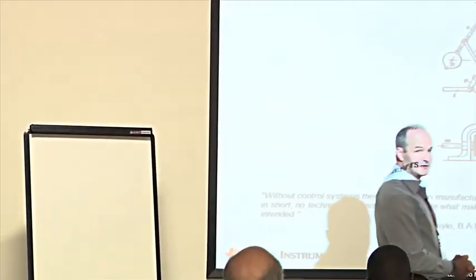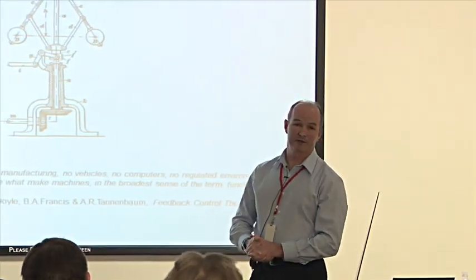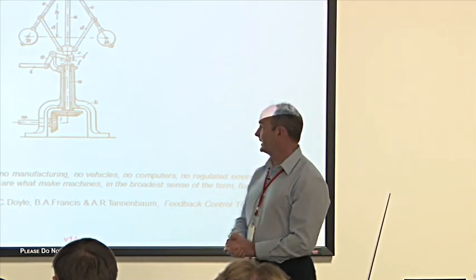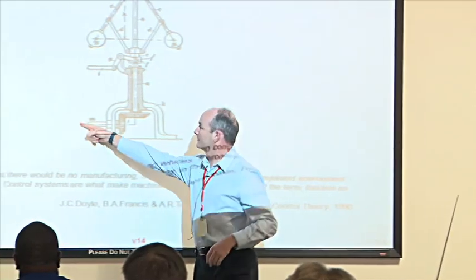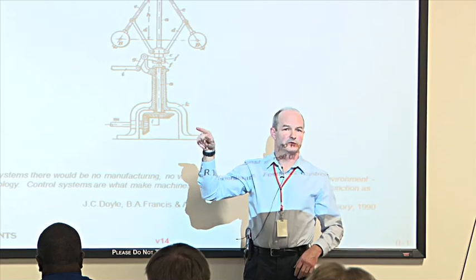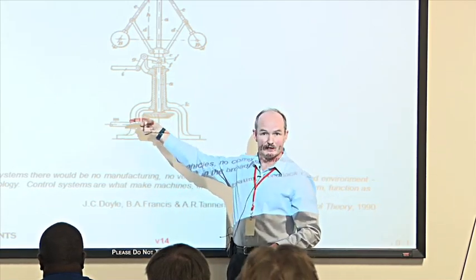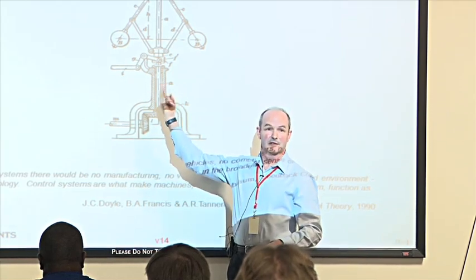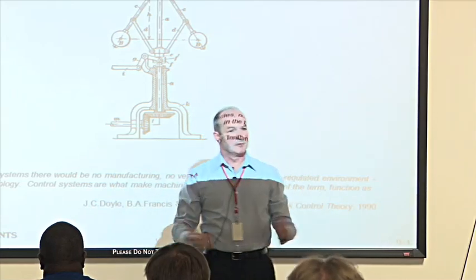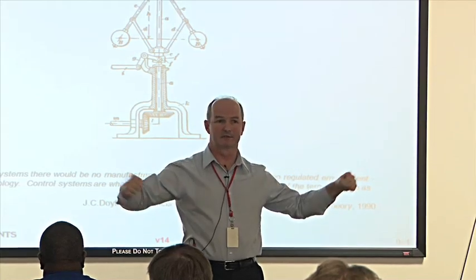It was invented in 1788 by a Scots engineer called James Watt. And its purpose is to regulate the speed of a steam engine. The shaft of the engine enters on the left side through this shaft marked M, and its rotational movement is transferred into the vertical axis by this bevel gear. So as fast as that shaft is spinning, this whole vertical assembly is spinning, and along with it, these two masses. And obviously, the faster the spindle turns, the more the centrifugal force pulls those two masses apart.